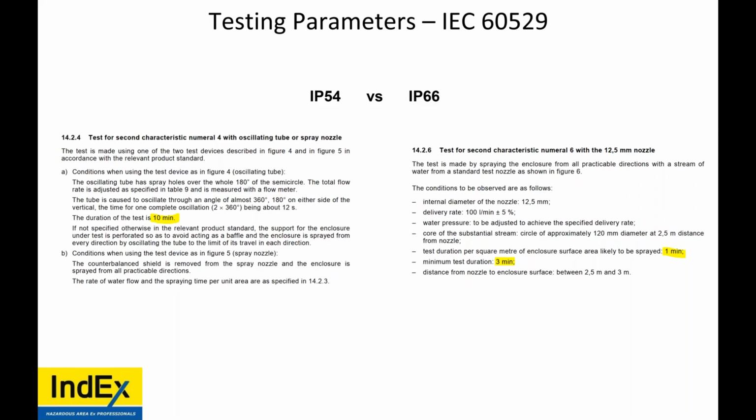Or 10 minutes? When it rains in certain locations like in Australia, offshore, Vancouver, New York, Chicago, wherever, it doesn't only rain for 3 minutes. And the force of the rain quite often does get up to about the force that an IP66 nozzle would be spraying at.